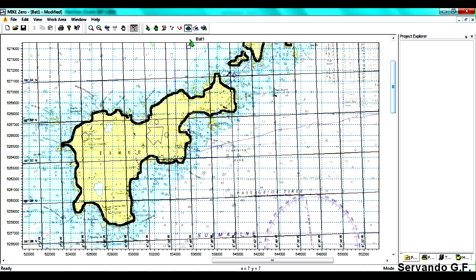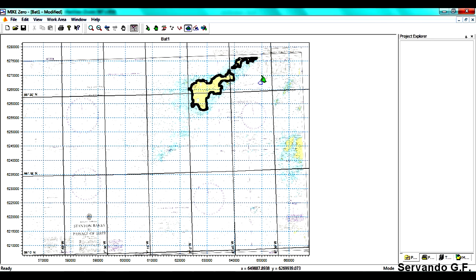Okay, so to save some time, let's say that you want to obtain the wave conditions here. It won't make lots of sense to spend time defining these areas, for instance, because the waves coming from here or here have a big fetch. It is the Atlantic, so they're gonna affect the area here a lot more than the waves that are coming from here.